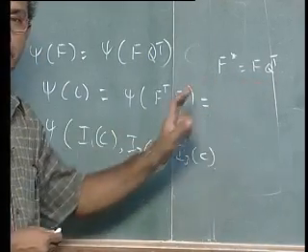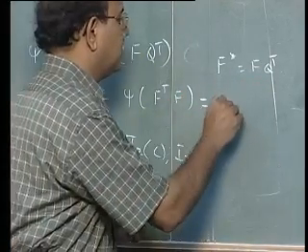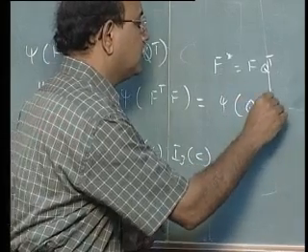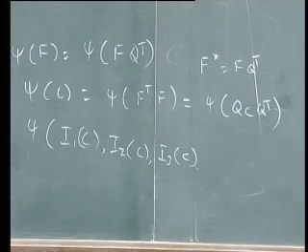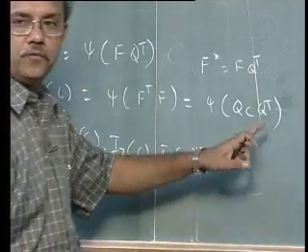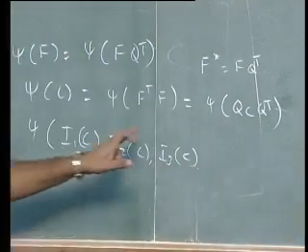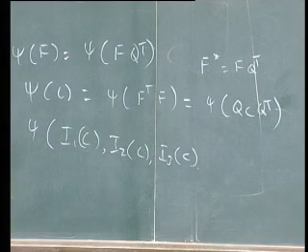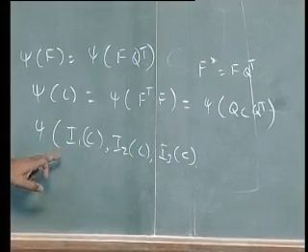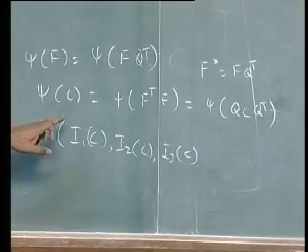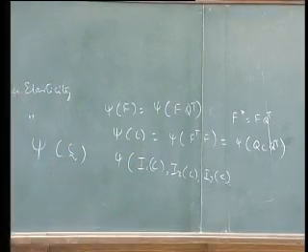So substitute from here, you will get that it has to be Q C Q transpose. Just verify that. If you have a strain energy function like this with this equation, then the representation theorem states that such an equation can be written in terms of the invariants of this tensor. What are these invariants, by the way?